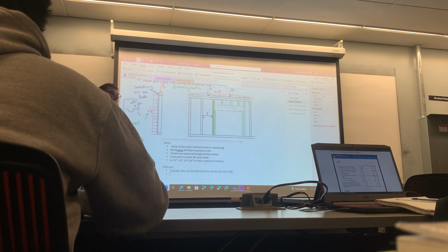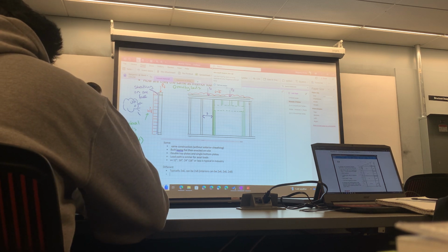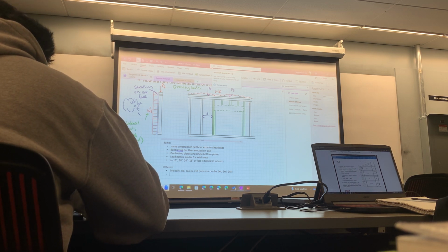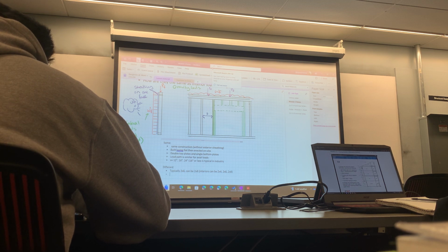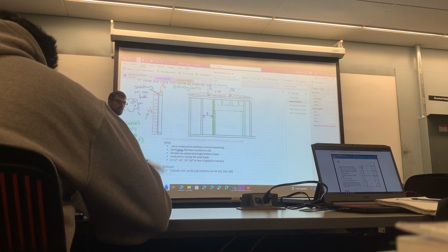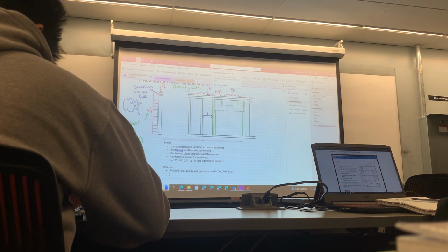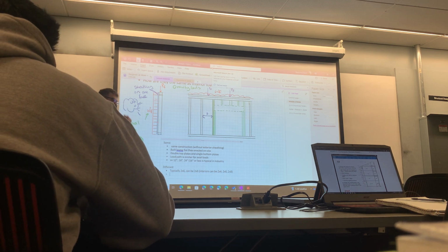And talk about the thermal bridge, and also how does the structure go? Yeah, that's my question. I've never seen that. I've seen a 2x6 with an interior 2x4 wall. The trouble with 2x6 is when you get into multifamily, like multi-stories, the 2x4s can't hold a lot of weight. So then the engineers will be like, 2x4s aren't desirable for gravity loads, and we want 2x6. And then the architects will say thermal bridging, not enough R value, and so we try to find a solution. I've seen 2x6 with a 2x4 wall inside, but typically I just see 2x6 exteriors.